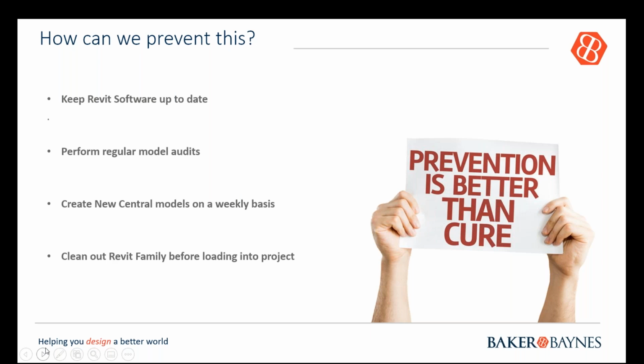You also want to perform regular model audits. So you can do that on the central model as well as the local model. Every time you're opening up a new local model, you can hit the audit button. You also want to create a new central model on a weekly basis.